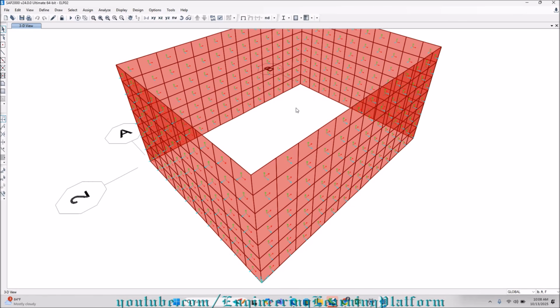If you want to simplify your process of applying loading, and apply the loads on all the walls in one click, you need to make sure the orientation of the local z-axis is the same for all the walls. So either you project all the local z-axes of the walls inside the tank or all outside the tank.